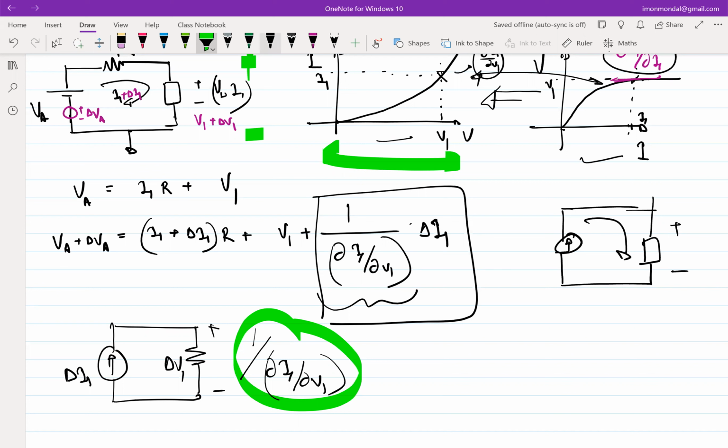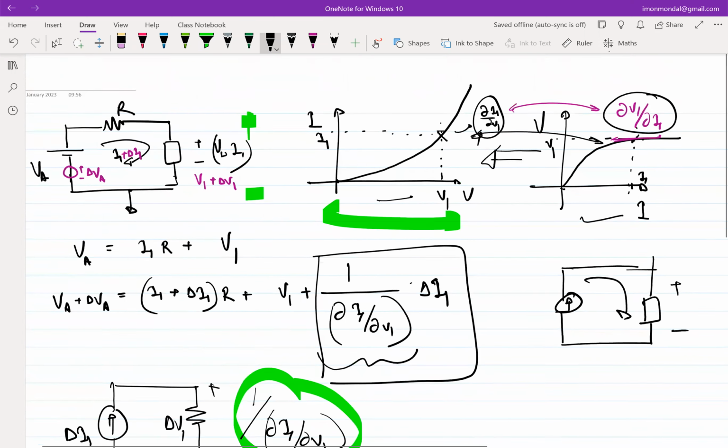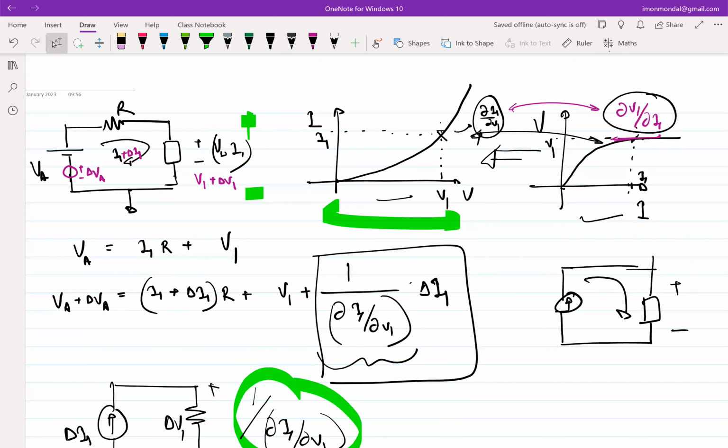Okay. Now, you have to be careful here, because this is one of the common mistakes. You will often see questions that ask you to find the operating point, find the incremental equivalent of the circuit, and so on. Initially, when you are starting off, you have to be careful to discern whether we are asking for the absolute voltage or the incremental voltage, right?